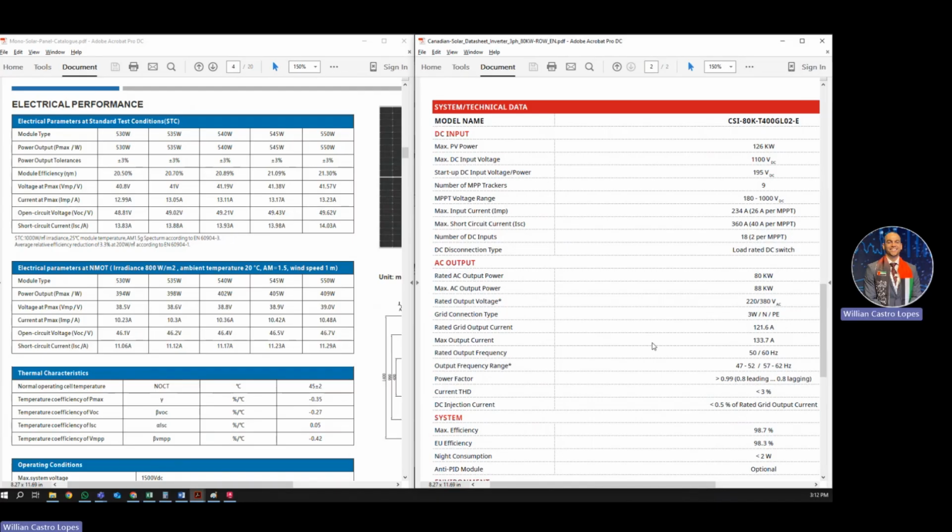For our calculation, verification and cross-check, if we can use this solar panel, what can we do? If I'm going to have 15 arrays of 10 solar panels, I have to check the voltage. How to check the voltage? If the voltage is enough and it's safe to connect the solar system, I can have a maximum of 26 amperes per MPPT.